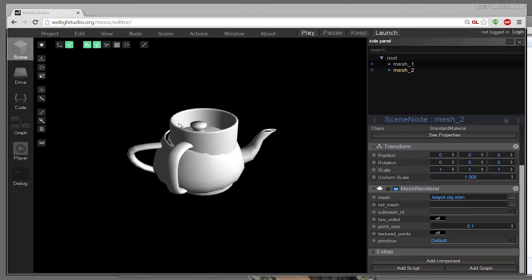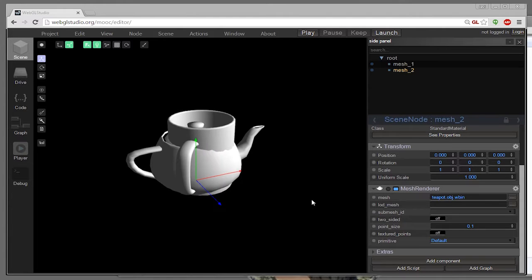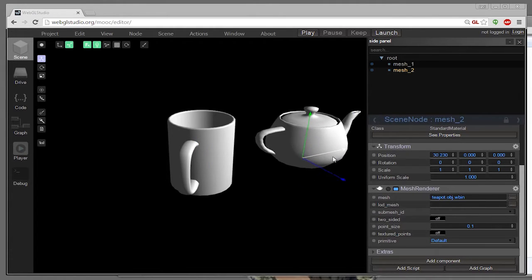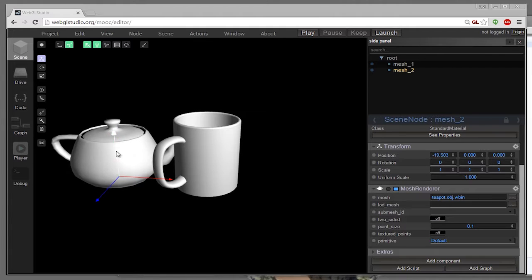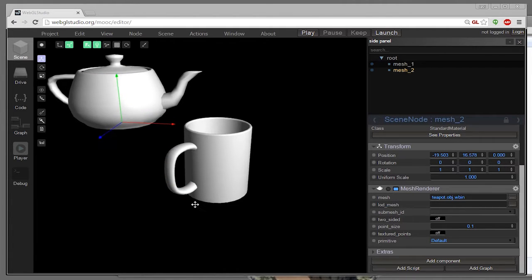So when you have 3D objects, the next thing you have to keep in mind is that to move the objects around, you should apply some transformations. To do so, usually there are different actions that you can perform. In these 3D environments, the best way to move objects is using these tools over here. In this case, this tool is the move tool. This kind of shape you are looking at right now on the screen is called a gizmo, and it helps us to move objects around. So if I want to move the object in that direction, I put the mouse on top of this axis and I drag it. Okay, and if I want to move it up or down, I can move it up and down.